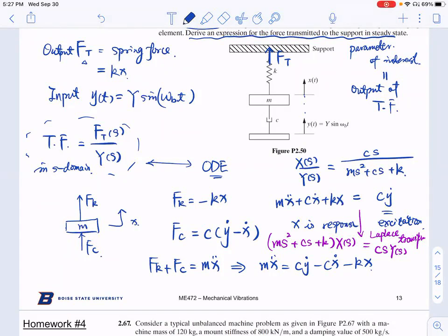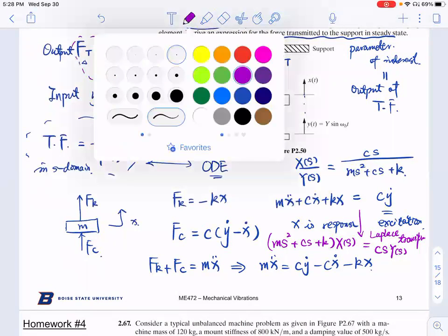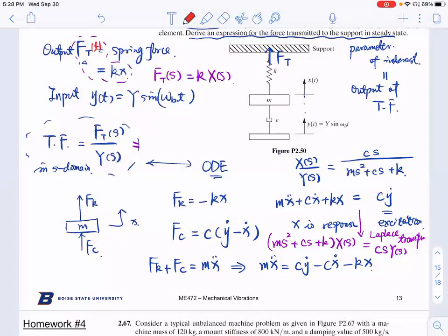All right, so remember the ultimate target is we need to find the force over the base excitation. But for your force, you have to go back to this equation. You do the Laplace transform on both sides, your Ft becomes F(s), and your x(t) becomes X(s). Remember this is a function of time, so you just do the Laplace transform for the time-dependent function.